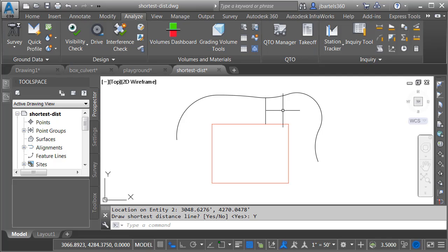I'm going to click the X to close the text window. I will then select this line segment, and I'll press Delete to remove it. In addition to feature lines and polylines, this tool can also be used with points, whether they be COGO, Survey, or traditional AutoCAD points. It also works with lines, arcs, circles, survey figures, alignments, and parcel segments.